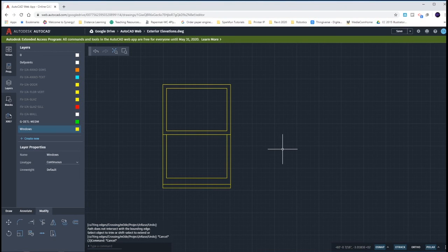Now for the upper portion of the window, I need 3 vertical lines that are equidistant from side to side. Well, I don't know exactly how wide they are unless I do a little bit of quick math. So if it was 3 feet 2 total for that, and I came in 2 inches and 2 inches, that means I am 2 foot 10 for the width of this line. 2 foot 10 divided by 3 doesn't really give me good math. But what I can do is offset by changing that 2 feet 10 into just inches. 2 feet is 24 inches, 10 more would be 34.